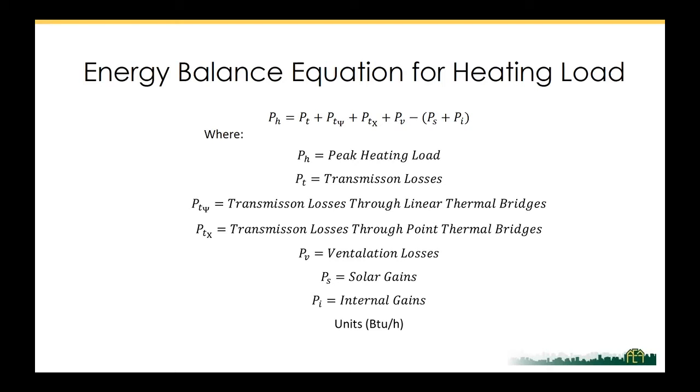And the solar gains, I apologize, but to get a sense of that, this is a new thing compared to the previous examples. So solar gains, what kind of contribution does that make to this overall equation? Solar gains are important. They reduce your heating load quite a bit. Especially in this case, there's a lot of shading. But the idea of Passive House is that you can design a house that utilizes solar gains, and you can even utilize thermal mass in order to create the most energy efficient house that you can. Thank you. Yep. And we'll go over each one of these individually.